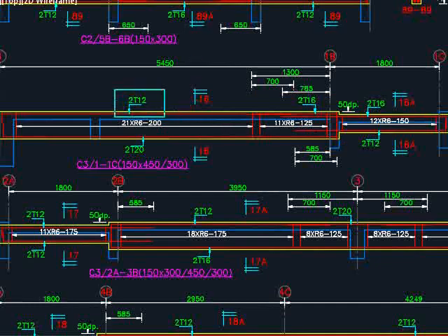Indicate the reinforcement bar required, indicate the shear length required, as well as the numbers of shear length, indicate the cut section, and also indicate the top main reinforcement bar at the support, as well as the required lapping when the bar size is different.